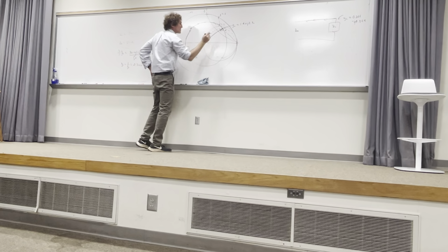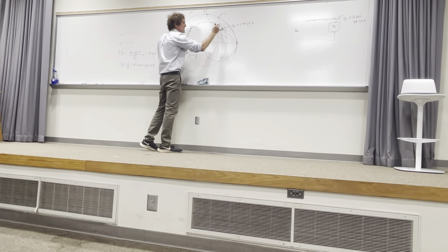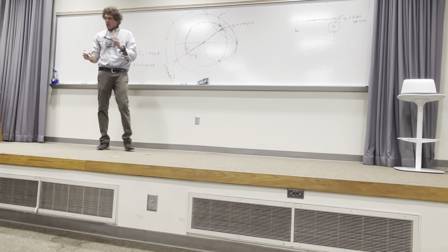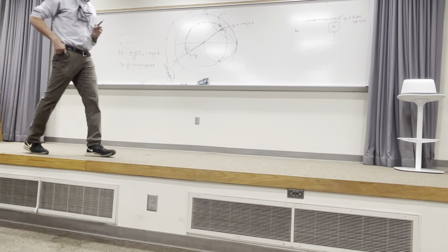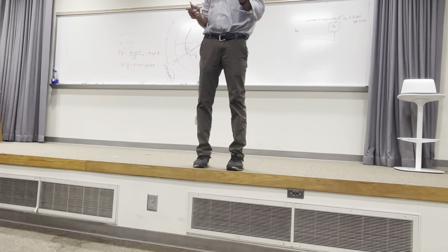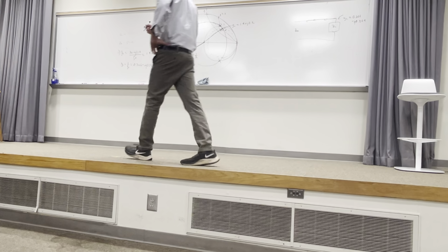Y'all with me? Now there's a caveat. There's 2 points you automatically mark up. Wherever this circle intersects the one circle, this is the first, and this would be the second. Y'all see those? Just mark them right now. We'll talk about which one to select in a second. Everybody with me on that? Now, there is going to be a condition or a limitation put on us by the statement of the problem. He says use an open circuit stub, which I'll get to in a second, but then there's a qualifier. What does he say next? Choose a solution that minimizes the length of the through line. The through line. Yes. Interesting. That person's being sneaky.